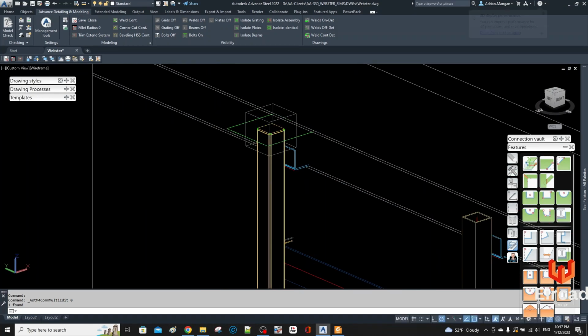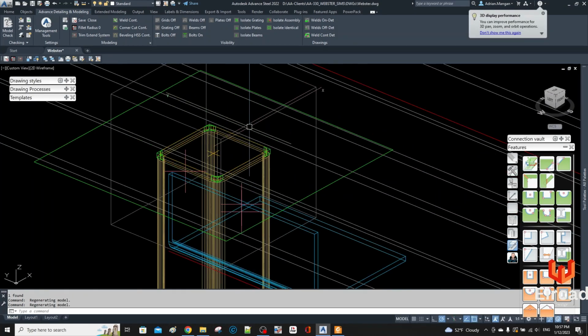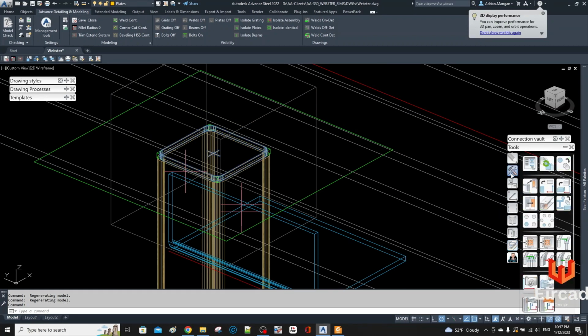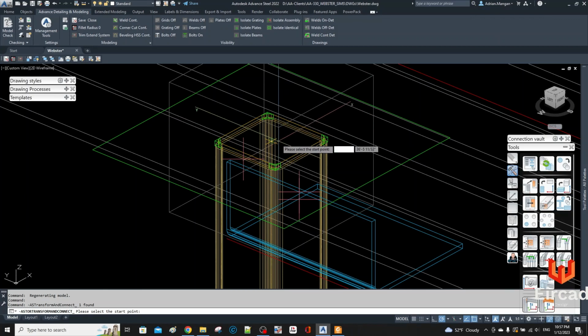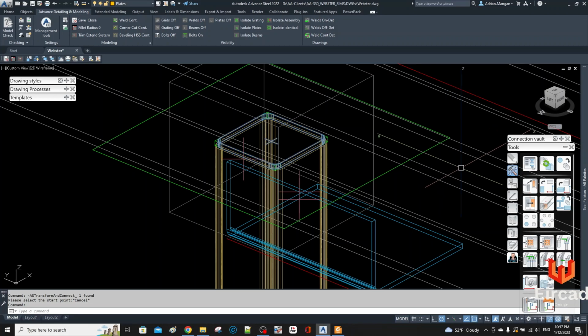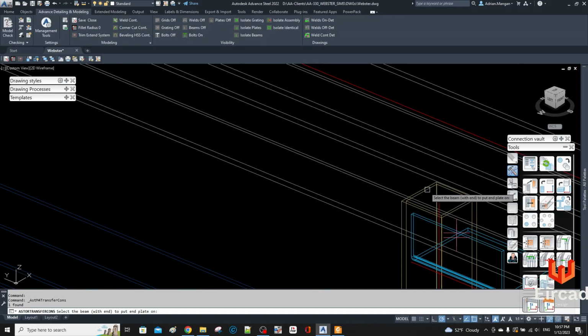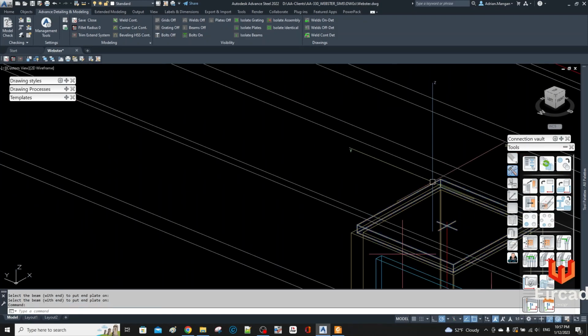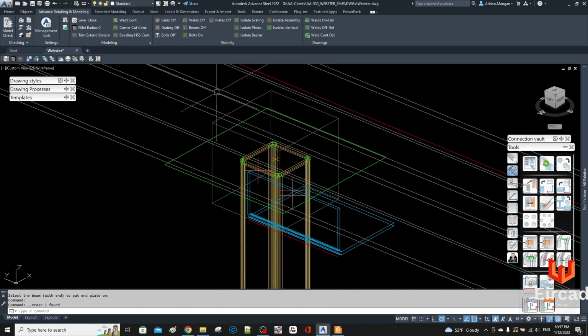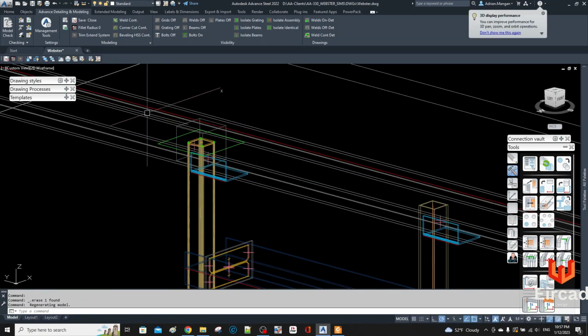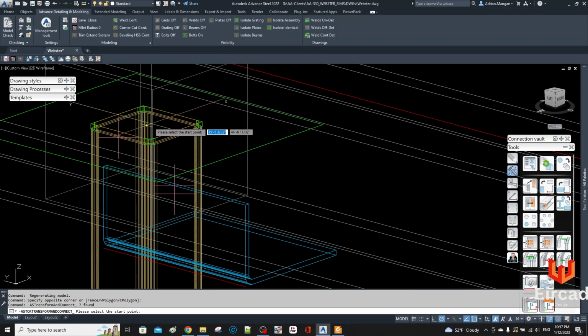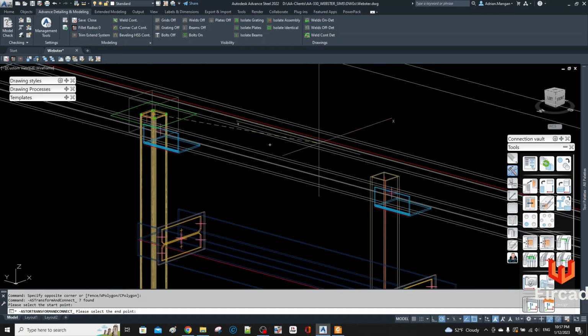Now, quick tip, I guess, you could just copy this, right? So if I copy this over, not copy it, so I guess I can copy the connection. So let's try it two ways. So let's click here and copy the connection over. It doesn't copy the corners, right? So now if I go and just select everything here, let's see. Once I have that box tick that I show you inside in here, this copy should work and bring all those features over, because I just selected everything.